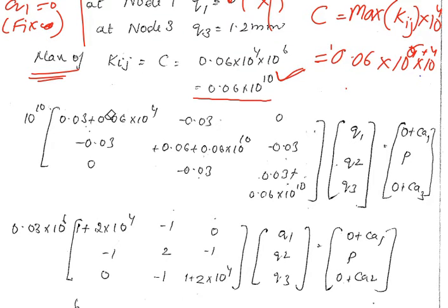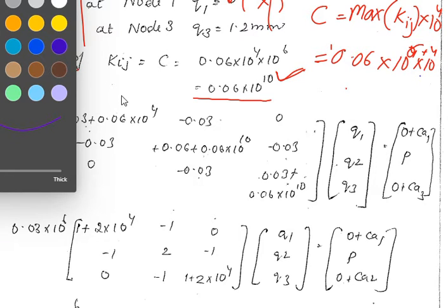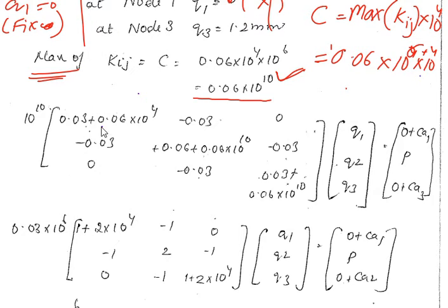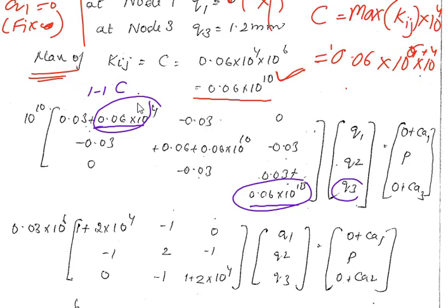So we can check that the c value is added in. You can just check here, this c is added here and another is added to this column. It means the first row, first column, at displacement 1, here it will be added, and also at q3. So q3 should be added, whatever the value you got, 0.0 plus c is added here with the existing value.